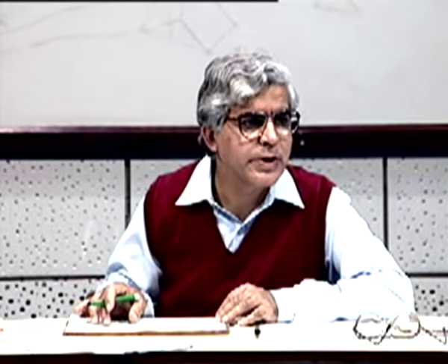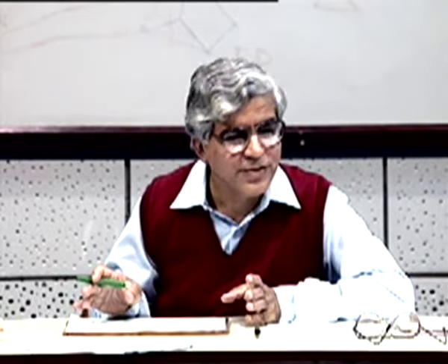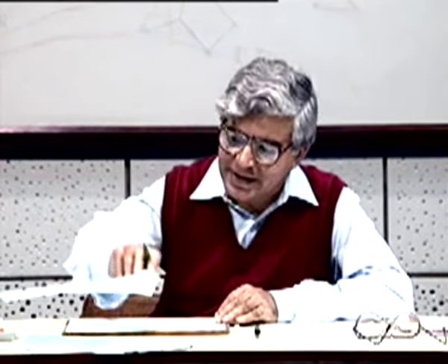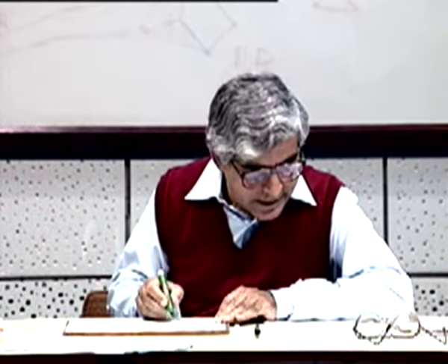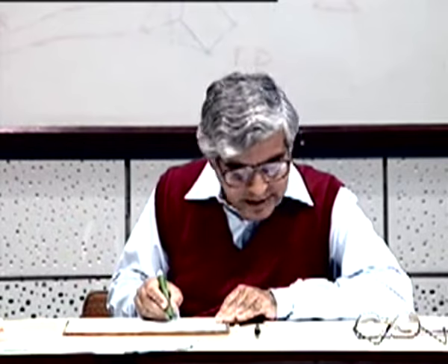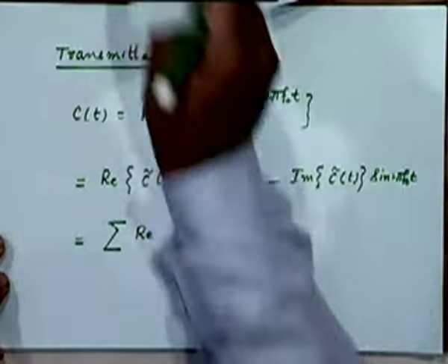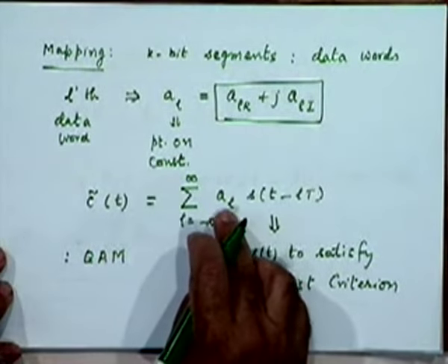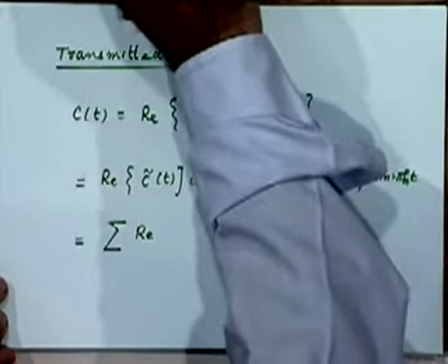When do we have a complex pulse shape? When can we possibly have a complex pulse shape? Okay, we go into that issue separately. At the moment, let's restrict ourselves to the situation where s(t) is real, so that we can take this to be essentially dictated by the real part of a_l and the imaginary part of a_l, right?